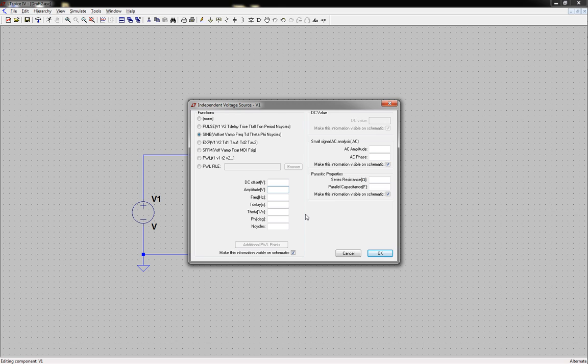If you plug a meter into a wall and you see 120 volt, you're actually seeing the RMS voltage, which RMS stands for root mean squared. Basically, it's the average voltage that is happening that it's showing you. So to get the amplitude of the signal, the actual peak value of the AC waveform, you have to do the square root of 2 times that 120 volt RMS value to get the peak value.